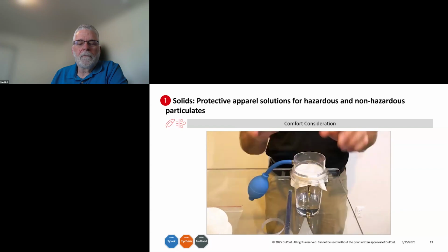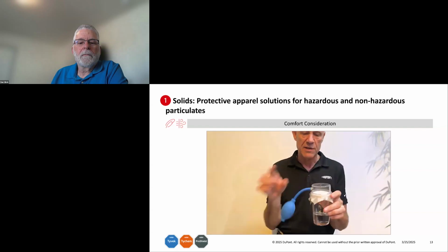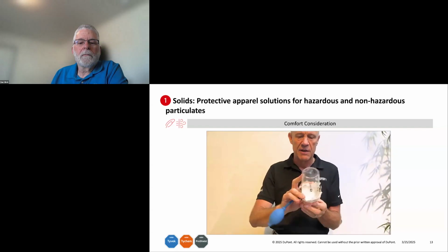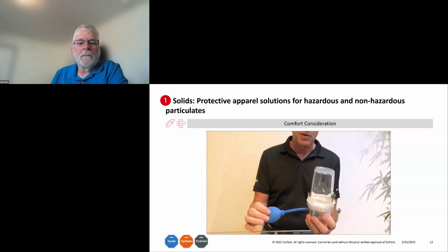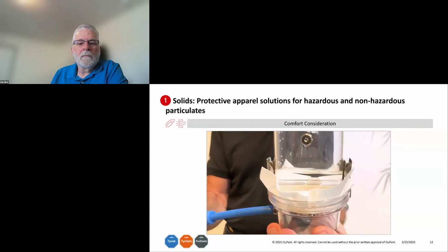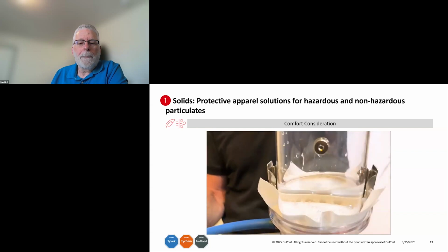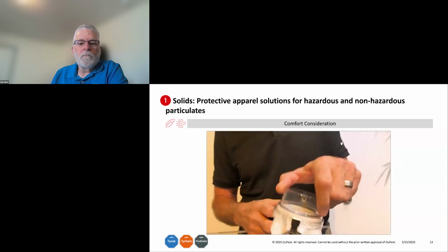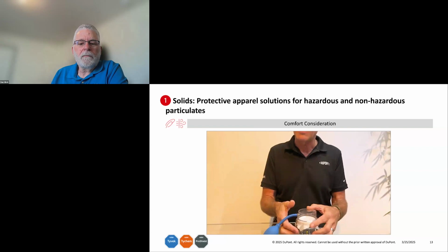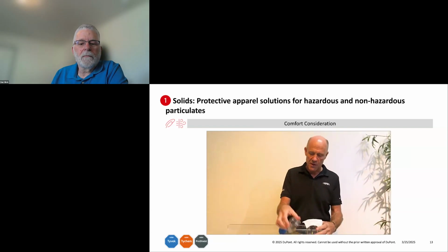What's going to happen is I've clamped it in this chamber. There's water in the bottom. I've got a bulb that when I squeeze it, it's going to put air pressure on one side of it. I turn this upside down. When I squeeze that bulb, if this material was breathable, you would certainly expect air bubbles to be coming through. It is completely unbreathable. It is a plastic coated fabric, and that plastic coating on there makes this completely unbreathable. So contrary to the manufacturer's claims, microporous film is not a breathable material.